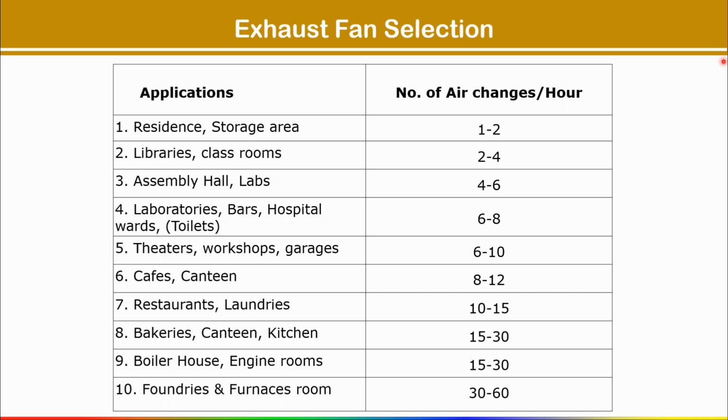Once you get this value in whatever unit, suppose you have calculated in meter cube per hour, so from the manufacturer catalog you have to search it. Meter cube per hour airflow rate value is given. As per that, you will get the model and everything.